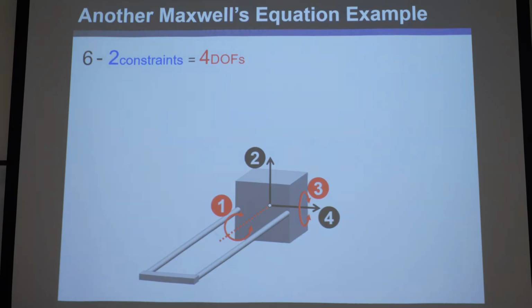Okay, so here we go. What's over-constraint? Well, let's look at this example here. Say we have this example, our famous example. This is grounded. This guy moves with 4 degrees of freedom. Now say we add this constraint, right there in the middle, right along there. Which one does that constraint kill? So now it's 6 minus 3, you expect 3 degrees of freedom. Which one does it kill? Okay, put me on pause and stare at it, and then I'll tell you the answer.